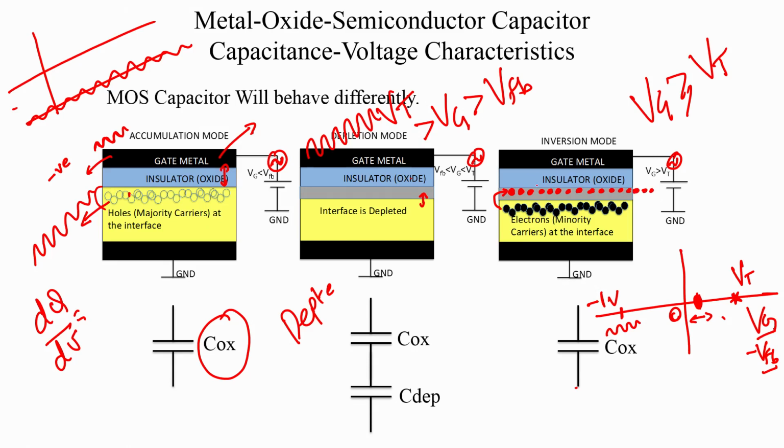So, the electrons are at the semiconductor insulator interface. You still do have depletion regions, but the electrons are between the depletion region and the insulator. So, they are at the interface. Please do make this correction here. And since the electrons are at the interface, any fluctuation of charge for Vg greater than Vt, we have crossed Vt and are now operating here, and any fluctuation in the gate voltage is going to respond to the electron population increasing or decreasing.